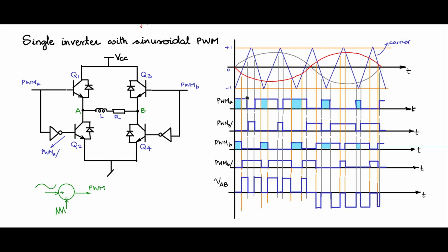That is, we turn off this a bit earlier, and we turn on Q2 a bit later, so that you can fix a period of time called the dead time period, when both Q1 and Q2 are off, so that you have ensured Q1 is off and Q2 is still not turned on. So this is a problem that we need to solve.